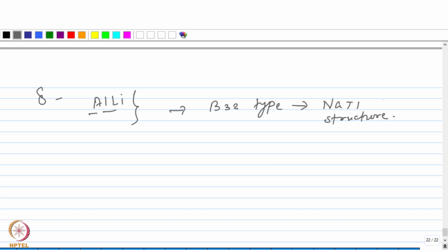Where you have two diamond cubic lattices penetrating each other. Okay, so two types of atoms that you have in ratio 1:1, they will form two lattices of a similar type, which is diamond cubic, and these two lattices will be interpenetrating. Okay, so that's the way to define the structure. So if you look at this particular phase now, the structure of this, it will be like this.